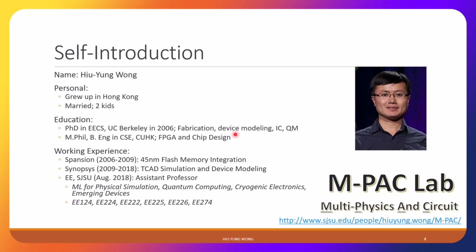At that time, people wanted to replace the polysilicon with metal gate to reduce the resistance and also reduce the so-called gate depletion effect. And the challenge of metal gates is to have the right work function. Right? So how do you choose the right metal in the integration process? At that time, people were still studying how to develop 65 nanometer. But don't worry if you don't know what I'm talking about. I hope that after this class you will get an idea about it, right?